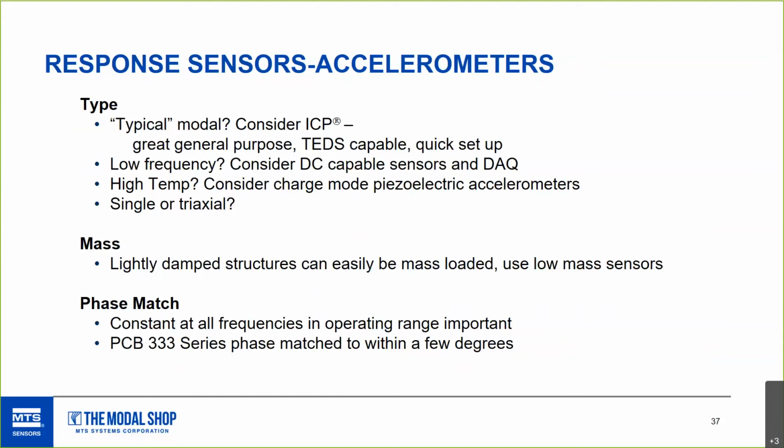For high temps, you can use charge mode piezoelectric. You can go up to 500F on some or higher. Yeah, or 900F, some higher. And pay attention to whether you need single or triaxial, or some points need to be a mix, or your test needs to be mixed.